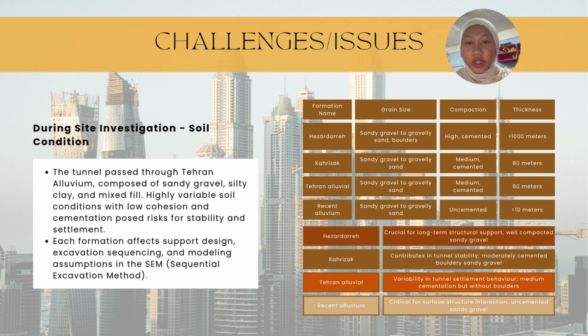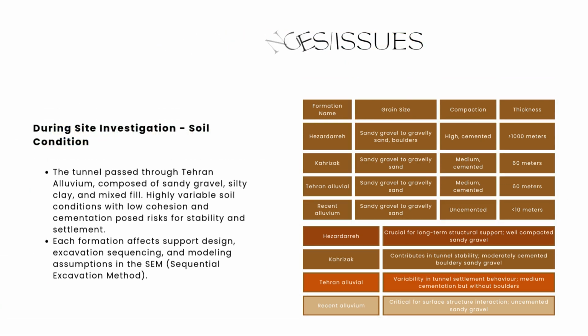Findings include formations like Hazardara, with over 1,000 meters of cemented gravel, crucial for long-term support, and recent alluvium, just 10 meters thick but highly influential due to its uncemented profile. This detail directly impacts support design and excavation sequencing under the SEM method.